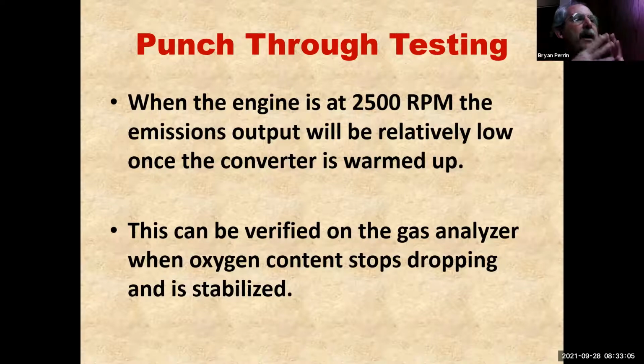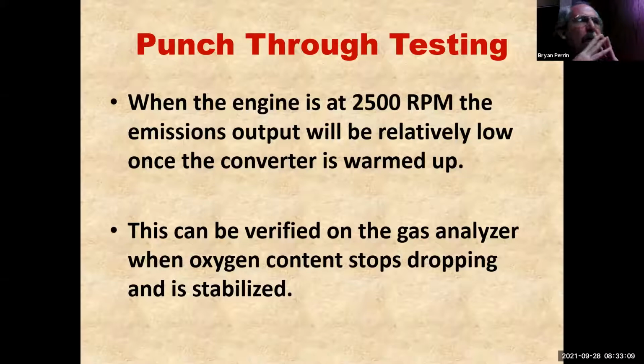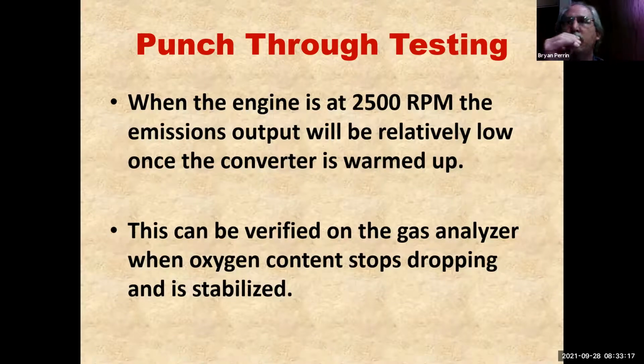So what I mean by watching the gas analyzer and the oxygen content, my catalytic converter is a net user of oxygen. When I first start up an engine cold, I'm going to see about 1%, 1.1% oxygen out the tailpipe. Once my car gets in fuel control and in closed loop, I'm going to see between 0.3 and 0.7%, probably closer to 0.7, oxygen coming out the tailpipe.